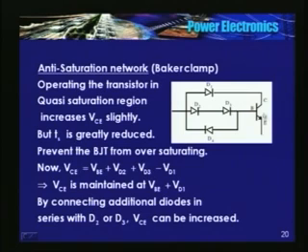Now with this anti-saturation network, what is the value of VCE? VCE gives a measure of the saturation level or degree of saturation of the transistor. See here now, this voltage VCE is equal to VBE plus VD2 plus VD3, these two diode drops, minus this drop.